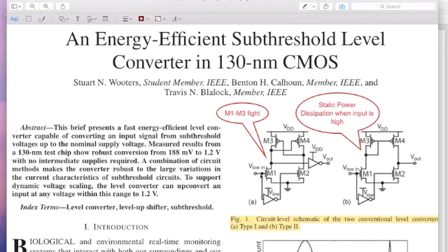But you have to fight against the PMOS M3. If my input voltage is maybe 200 millivolts or 300 millivolts, and my VDD to which I want to level convert is at 1 volt or 1.2 volts or even 2.5 volts if I'm the IO, then my PMOS is very strongly on. It is in the super threshold region. And this weak NMOS has to overcome that PMOS, and it will fail. You have not even turned on the NMOS, practically speaking, and you want to pull this thing down, and that is where we have a problem. So as the difference between the transmit side and the receive side levels becomes very large, this kind of structure doesn't work very well.